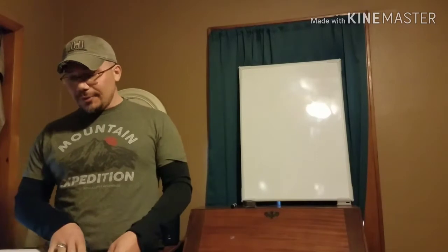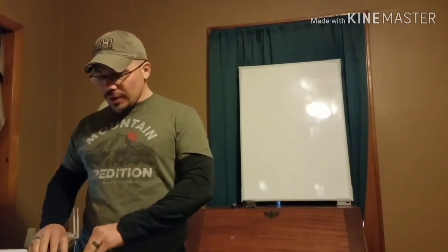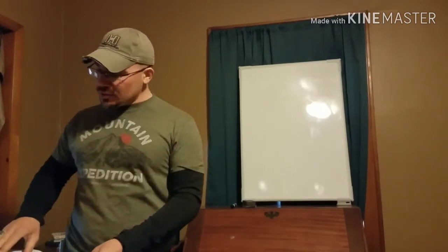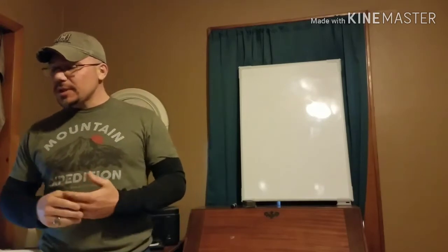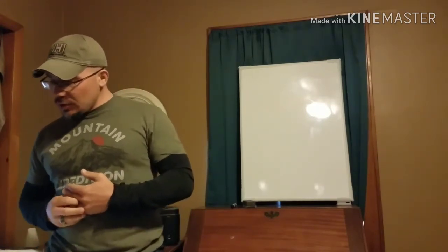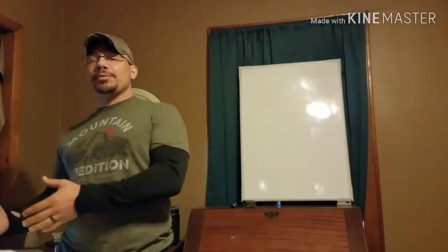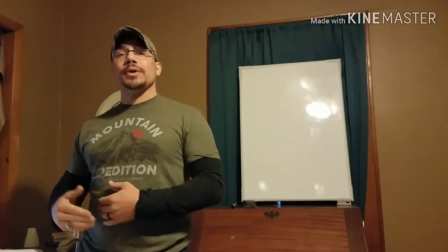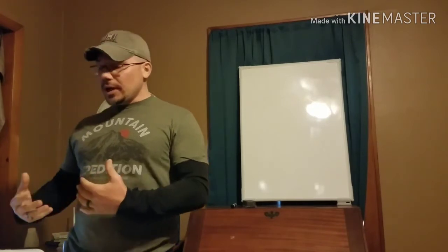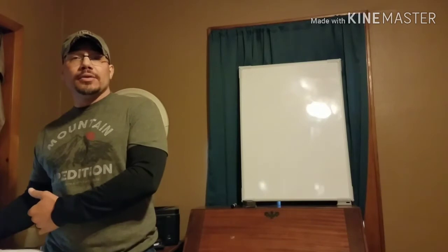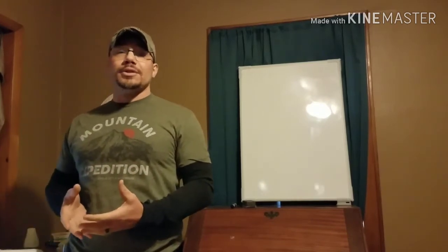Okay, so we're going to start in Article 220 at 220.54. If we go to 220.54, it tells us that for electric clothes dryers in dwelling units, your total load is going to be a minimum of 5,000 VAs. But if the nameplate of your dryer is more than 5,000 VAs, we have to use whichever is greater. So if you have a smaller dryer that's less than 5,000 VAs, you use the minimum 5,000. But if your dryer is, let's say, 6,500 VAs, then you have to use that nameplate number, because it's the largest of the two.